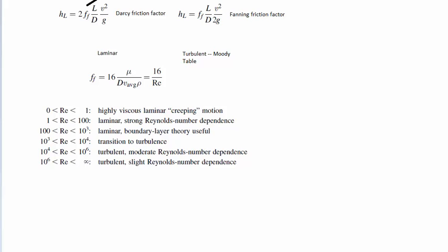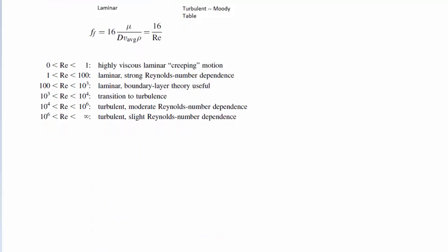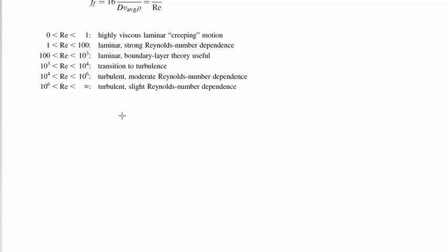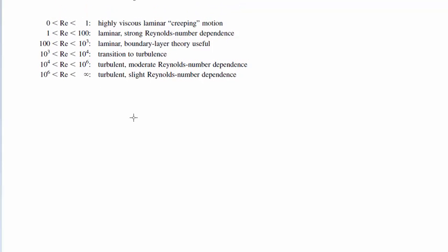The difficulty is that there's certain things, flow pattern being one of them, that depend upon the actual parameters in your system. So they depend on the intrinsic velocity or viscosity or diameter of the inlet or density. And then you're stuck, unable to proceed with your general equation until you know more information about the system. Well, this allows you to, once you get to that fork in the road, say, let's solve the system assuming it's turbulent, or let's solve the system assuming it's laminar. And you could determine that from your input parameters, because you'll know your Reynolds number, and then be able to decide the flow type that you're dealing with.